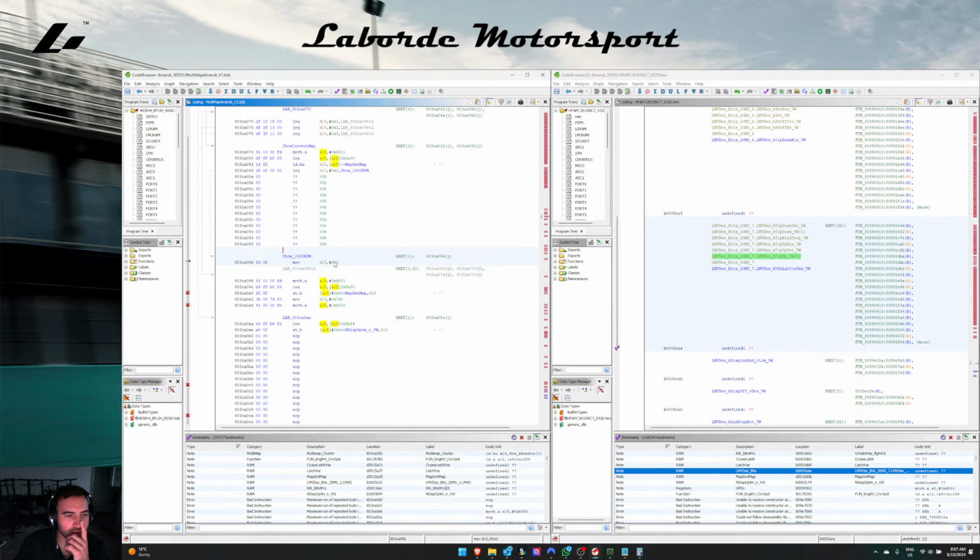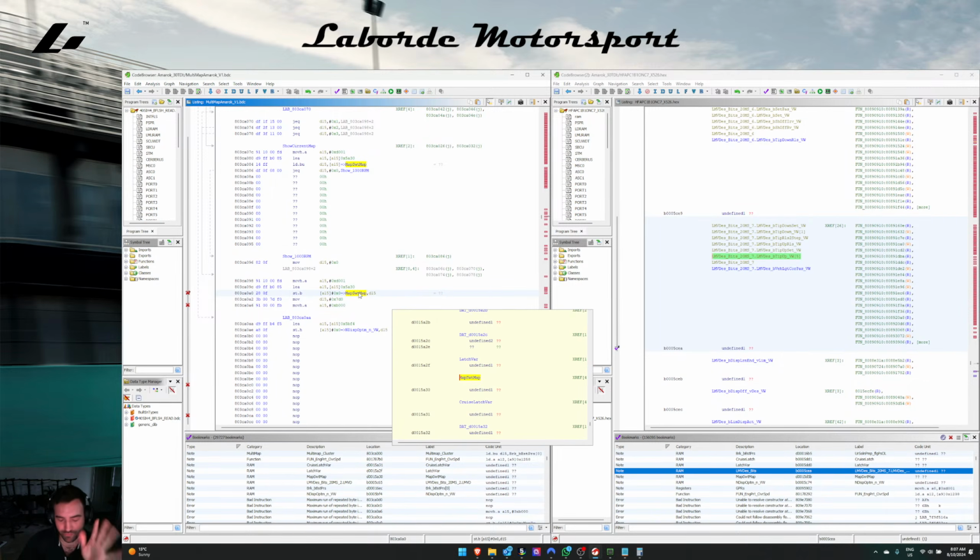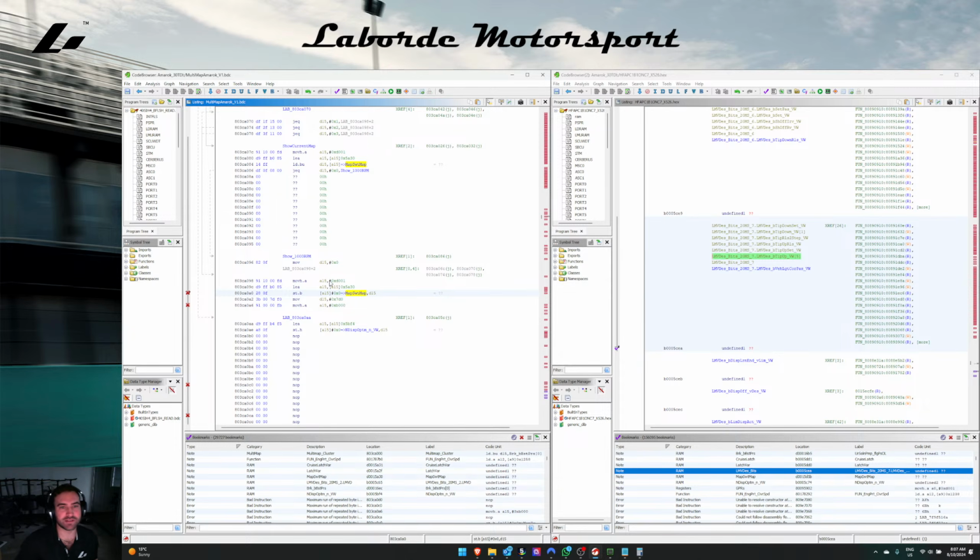So 0 is our map that's being stored into our map switch map in RAM, which is EEPROM, is RAM mirrored to the EEPROM, which then will save it when we turn the car off and we can start it up again. We're moving the value of 1000 RPM, which is 7D0, into D15, and then we're storing that high in the engine speed variable, and then when we're returning, okay, then I'm going to make this show 2000 RPM, right?